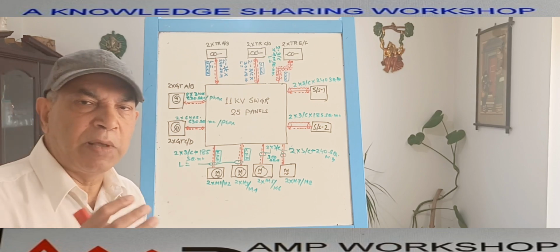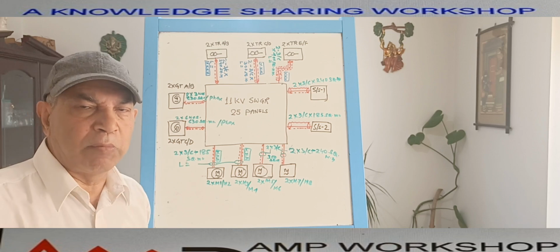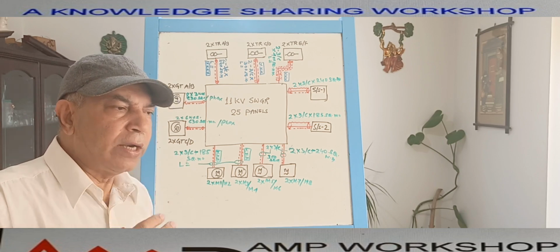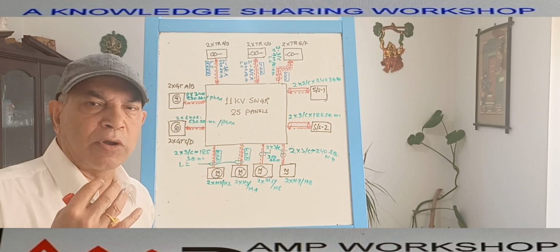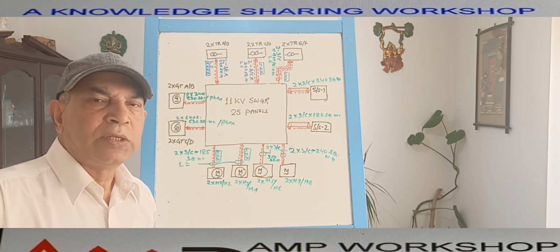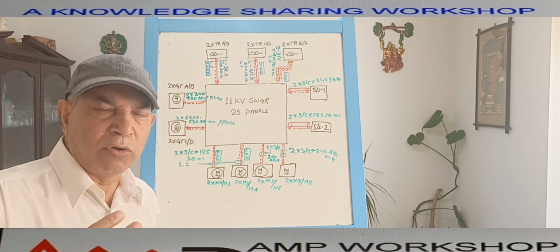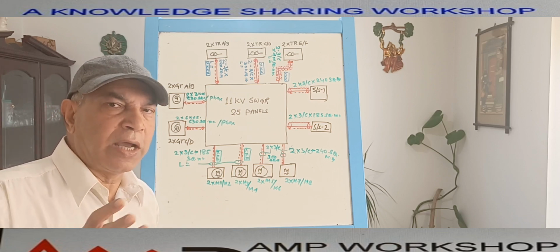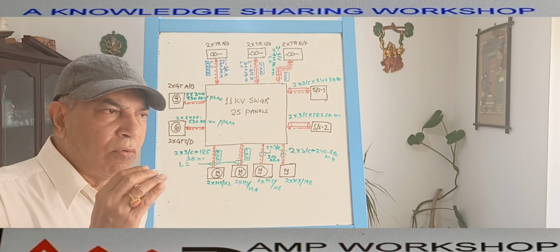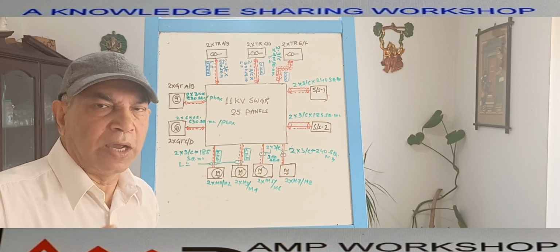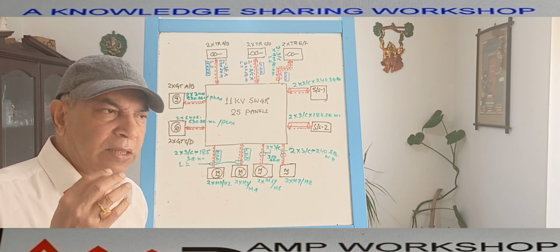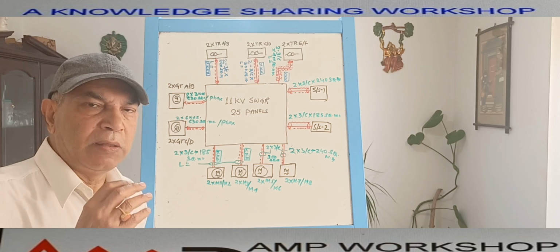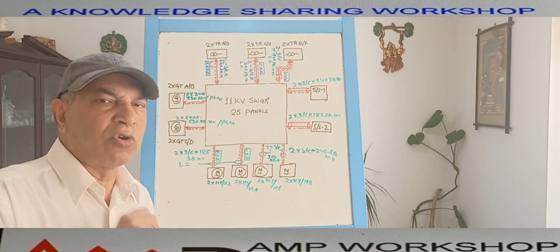When we represent the block diagram for the power cables, we say it is a power cable block diagram. If we represent the block diagram for the control power cables, we say control power cable diagram. Similarly, when we represent all the control cables, we say control cable diagram. This way the cable diagrams are designated. Now, what can we represent in a cable block diagram? In the case of power cables, it is easy to represent all the power cables and the various information on the same drawing.